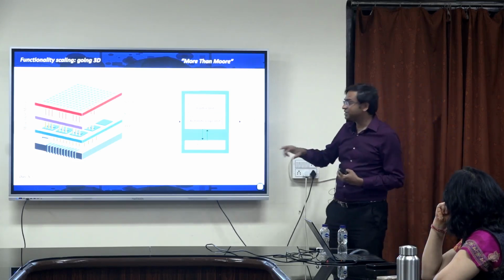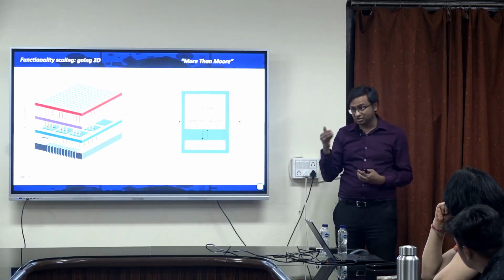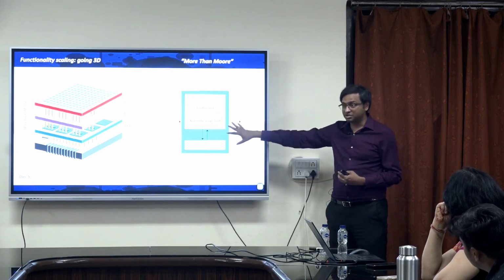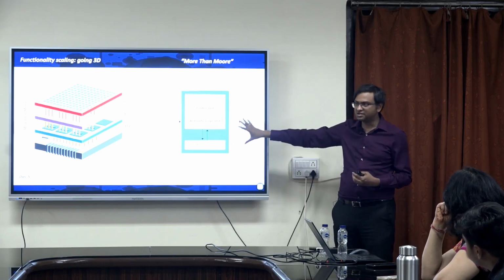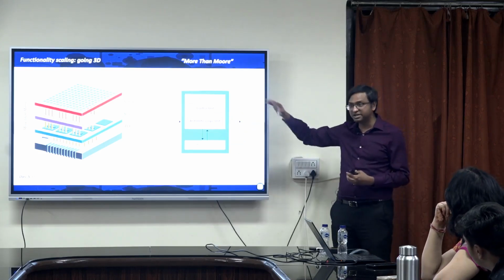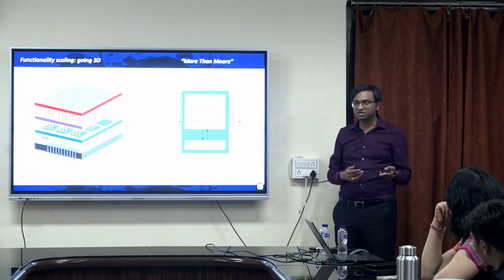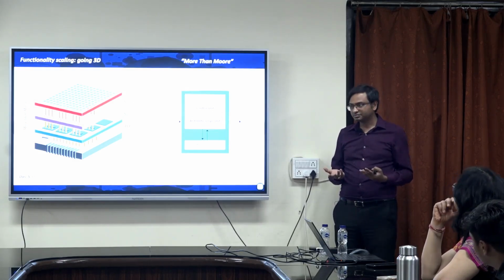So, we have to start doing 3D also to address the critical need for artificial intelligence or neuromorphic computing, because of this problem that we had a lot of discussion on, the neuron and synapses and the separation between logic and memory. So, now in this 3D chip, you can dedicate one tier for memory, one tier for logic, and they are right next to each other, correct.